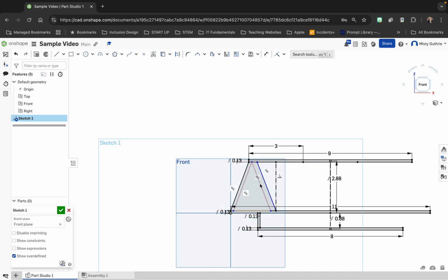We can look at it and tell these are not the same width. Watch carefully. These are diagonals, and I've mentioned repeatedly how easy these were to dimension. When you're going across a diagonal, you need to do it across the middle. So click the first one, then click the next one, and it will switch because it knows you're doing a width, and then make it 1/8.